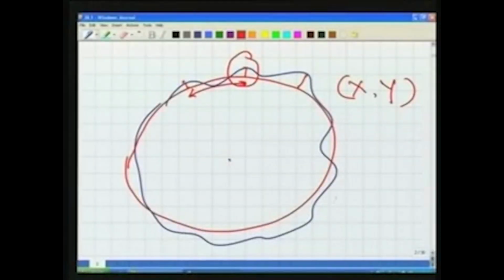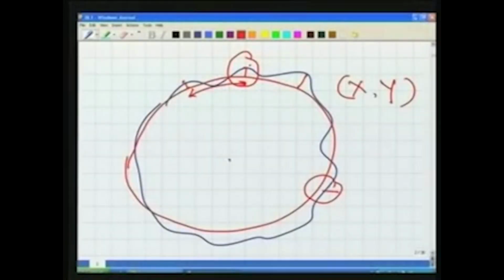So the Mount Everest is somewhere in one part of the world, while the Alps are in other part of the world. So in order to compare these two, we need one single reference which is passing through both of them, and then only we can compare the elevations of these two or the heights of these two. So for this purpose, we need one reference system. Well, we are talking that our reference system is ellipsoidal here, and any two distances that we are measuring between point A and, for example, point B here is the distance along the curvature.